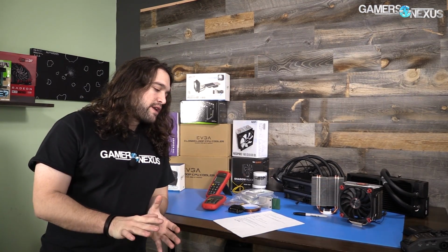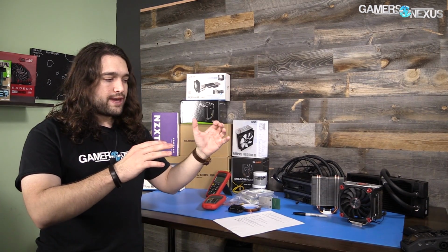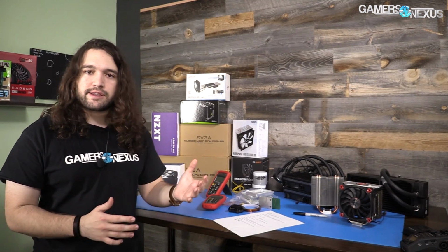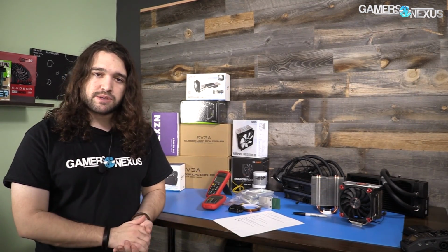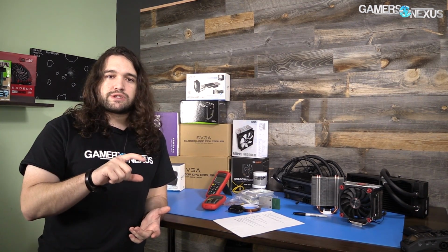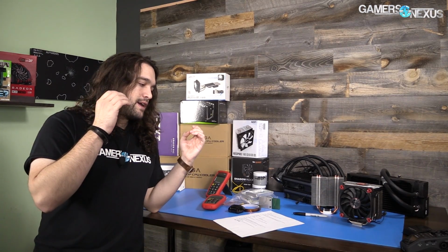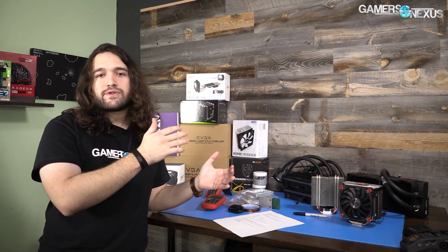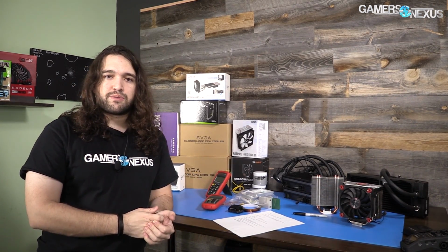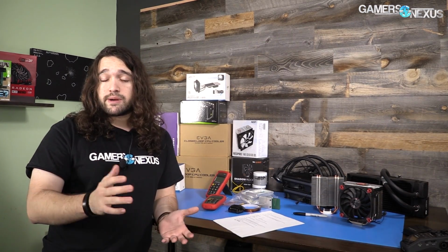And once you've run that test enough times, look at the data and try to understand, is it the same? What is my variance? If you've got a variance of about a degree and you can't get any more accurate than that, which is possible, then it's time to add a little note to the charts and say, my temperatures have a variance of plus or minus 1 degree Celsius. And so then you can say, if we've got a cooler that's measuring at 51 versus another one at 52, they are effectively identical. You cannot do any further validation to prove that one is better than the other. And of course, functionally, they're basically the same anyway, even if those hard numbers are accurate.